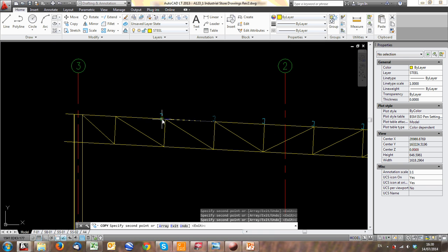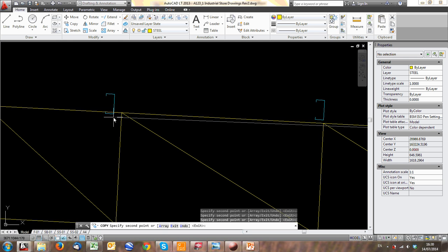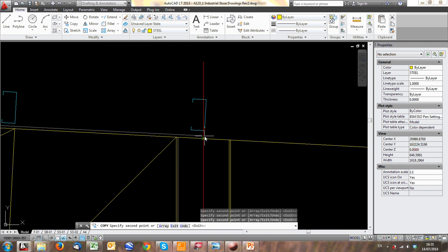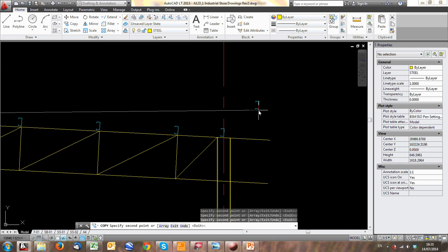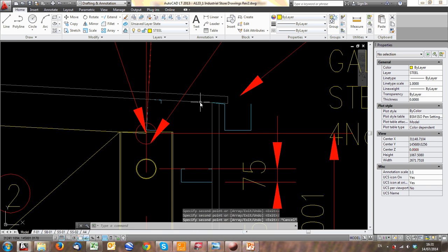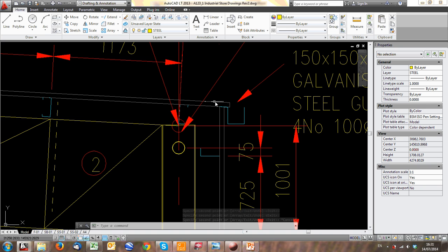Great. Up here. This last one you have to be a bit careful of. You need to see how you will fix it to it, because you need to keep this cantilever distance down. If your sheeting is only allowed to cantilever certain distances, you need to maybe move it up, because you could put that cold form there, just to the left of the column, and it might be easier there, but this sometimes becomes too long. So either you can bolt it to the top of the column or put a section there to fix it to.